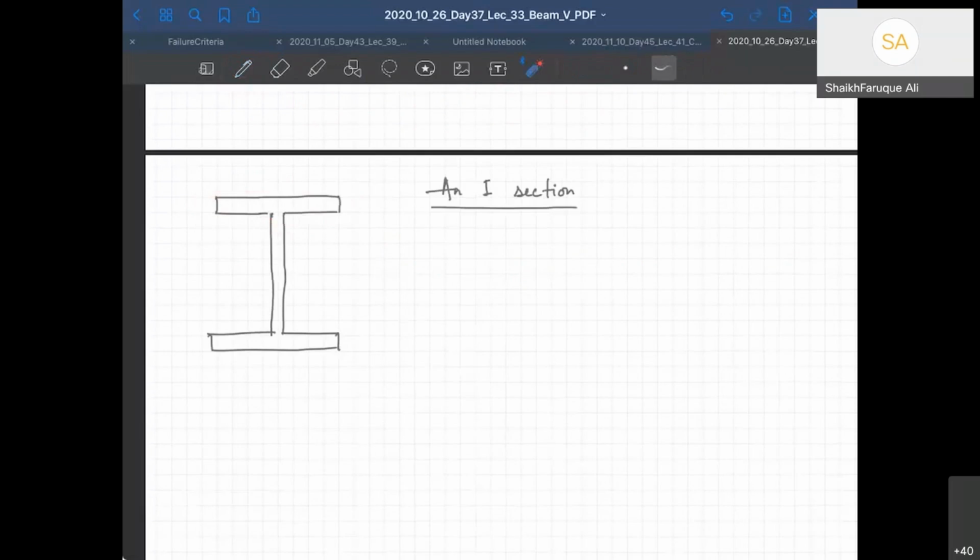We'll be happy with it also, because when I design a cross section, I will not design that cross section based on the values that I get at those areas, right? We will design the cross section based on the values that we get in the maximum point of view. Okay, so I'm not going to design my cross section based on these stresses. We will design the cross section based on the stress here, right?